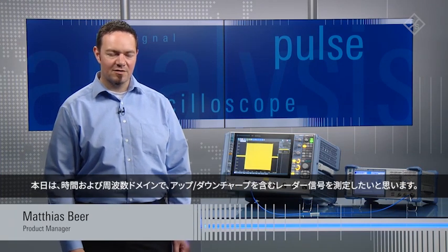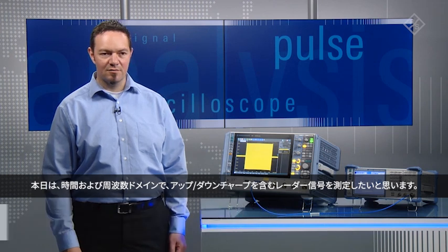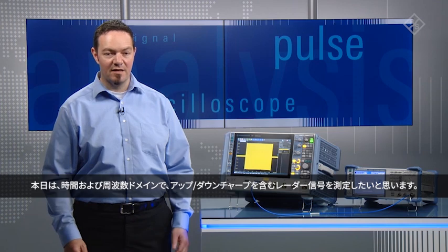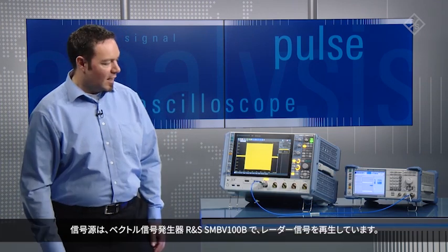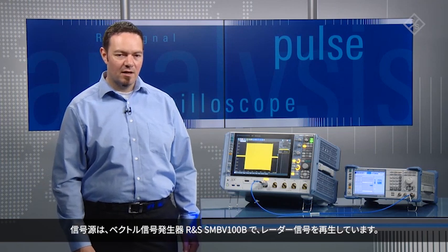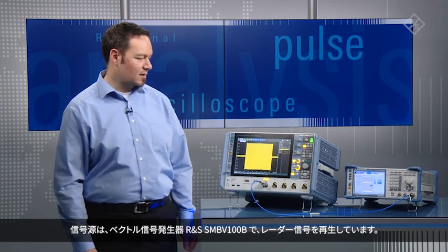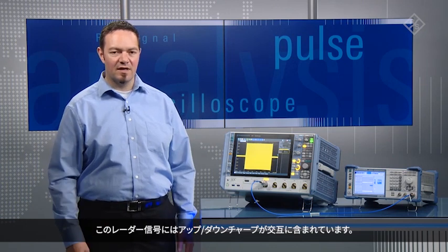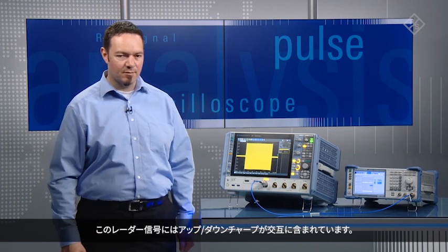Today we would like to measure a radar signal which includes an up and a down chirp. We want to measure this in time and in frequency domain. As signal source we use a vector signal generator SMBV which plays back the radar signal, and this radar signal includes alternating up and down chirp.